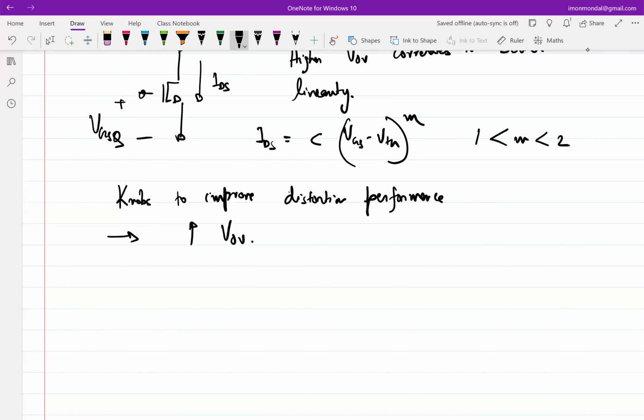If you use negative feedback, the loop gain should be high enough at those frequencies. So let's say you want like 20 dB loop gain at 2 gigahertz, I'm just throwing out a number. And if you want this 20 dB per decade roll off, which means the UGB should be like 10 times that of 2 gigahertz.